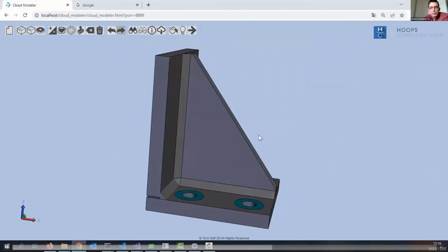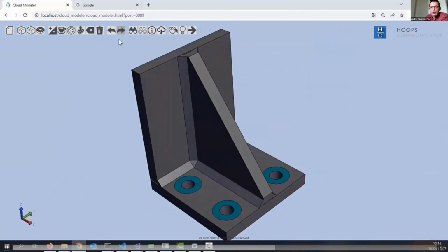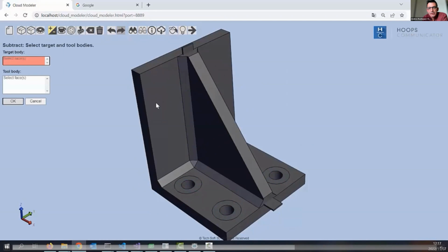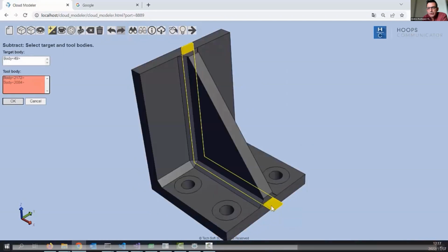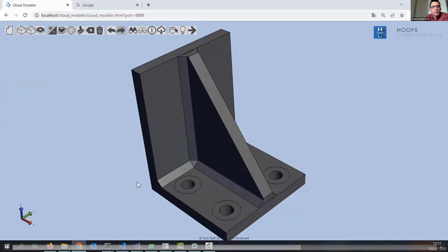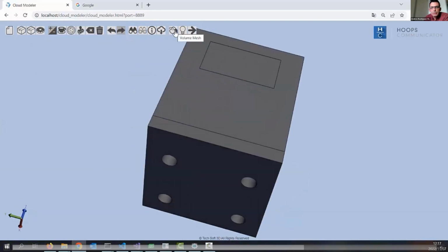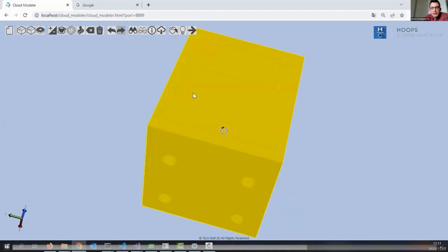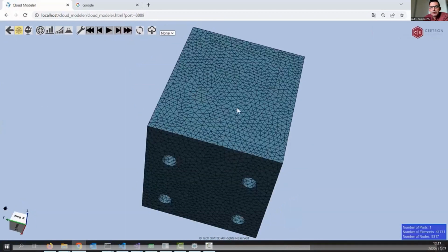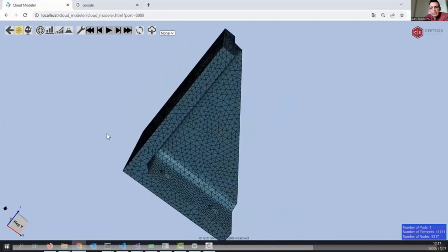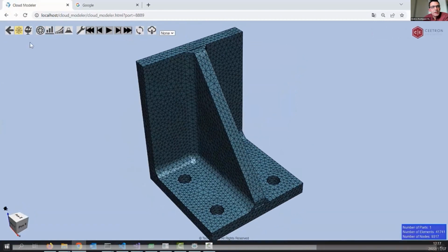So we go back to the design screen, and we're going to model the weld that joins the two plates as a groove weld. And in this case, the plates will be fully connected, so we get rid of the gap we created previously by using Parasolid's undo to remove the thin plate artifact, and then the union Boolean operator to join the plates. The other welds remain as fillet welds, so we'll keep the gap, and we can regenerate the mesh and move back to the simulation screen, just powered by ENVISION. No change in the boundary conditions, so there's nothing to do at this stage.